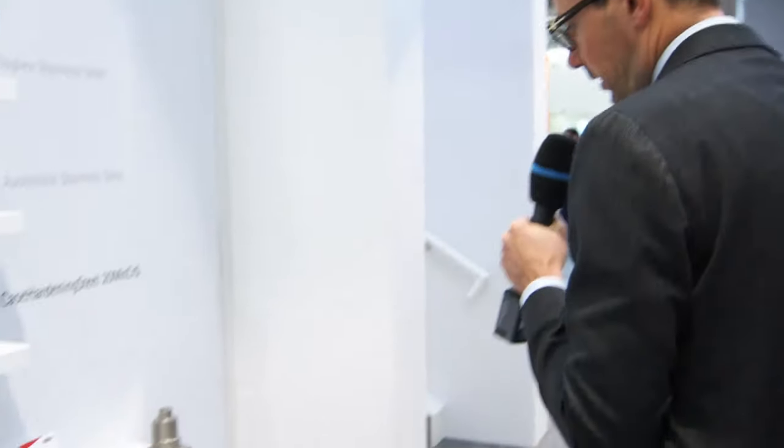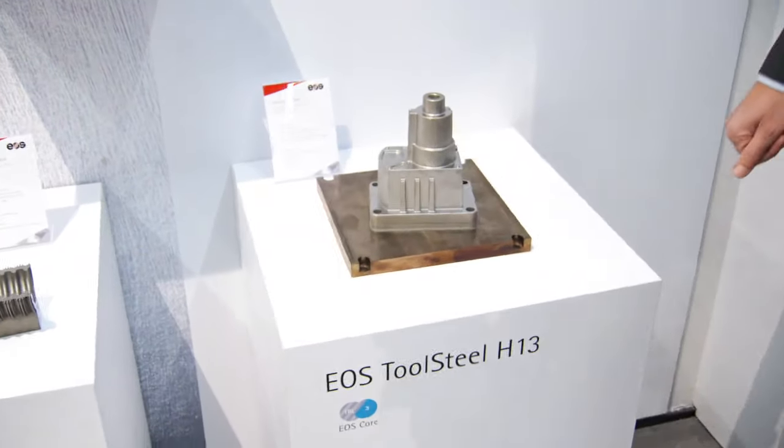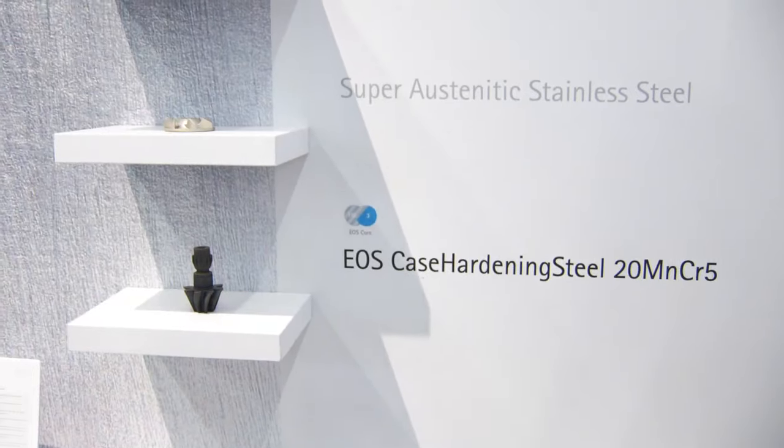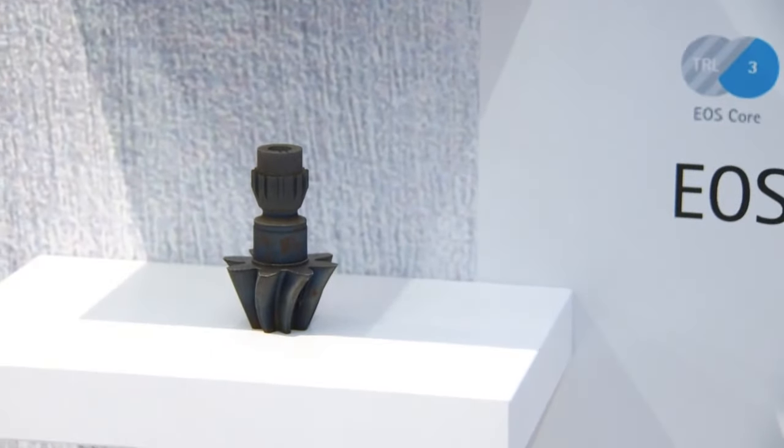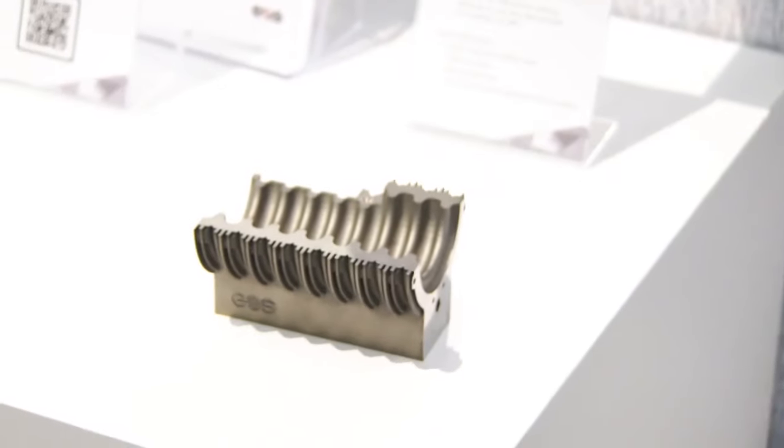And thanks for mentioning it's hard to weld, because that's actually true for most of the materials you see here, and that's why it's really great that we managed to develop all these different materials, even though they're so hard to process. And the same is true for these steels. Here we have a hot working steel, H13, that is used for die casting, for instance. We have super austenitic and super duplex steels. All of these are very hard to weld, and it was quite a development, and it's always great when something hard finally leads to results like this.